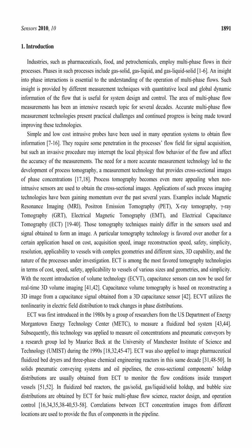The area of multi-phase flow measurements has been an intensive research topic for several decades. Accurate multi-phase flow measurement technologies present practical challenges, and continued progress is being made towards improving these technologies. Simple and low-cost intrusive probes have been used in many operation systems to obtain flow information. They require some penetration in the process's flow field for signal acquisition. But such an invasive procedure may interrupt the local physical behavior of the flow and affect the accuracy of the measurements.